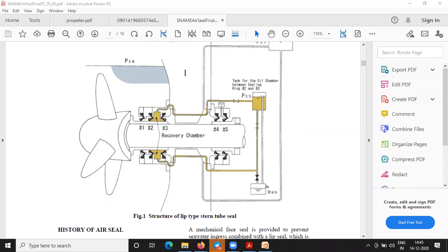Sir, we have two different gravity tanks also, for low draft and for high draft. Yes, so we change between low draft and high draft, because the pressure has to vary according to the draft. If we have a pump, it will keep giving us the same pressure, which we don't want. And also including a pump is not economical. Why would you want a pump when it can be done without one?